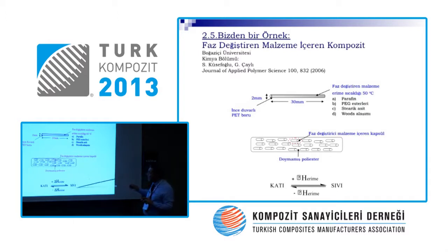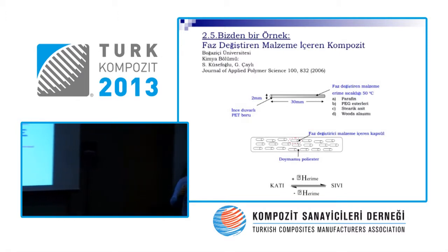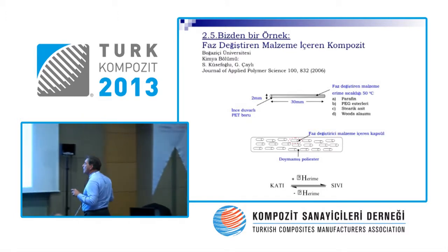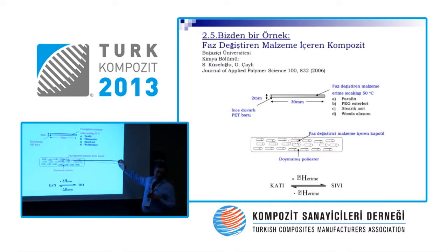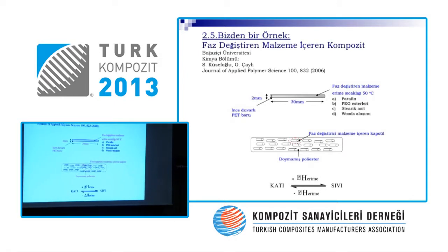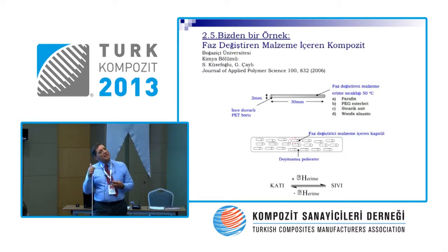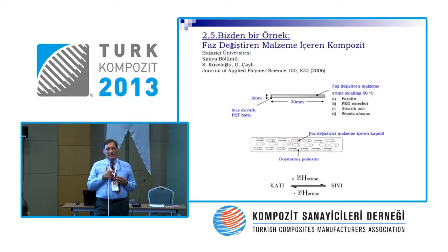Can I use this change of temperature as a heat storage method? Yes, actually it's working well. When I heat this to more than 50 degrees, all the materials in these capsules will be liquid. And when I leave that material for cooling, when it comes to 50 degrees, all the materials go solid, and the enthalpy energy will go out. So the enthalpy energy I put in will be delivered back here.